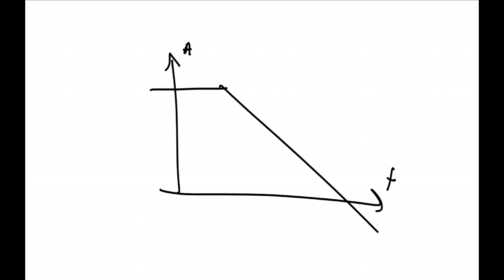Normally, if you have a lot of gain, this is a fairly low frequency pole, which means you normally operate up in this area here. So actually, the DC gain is not really that important. What is important is your gain bandwidth, because you probably don't spend a lot of time at DC. You might spend a lot of time up here where your signals are, but that depends on the application.